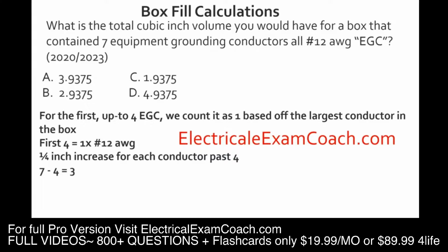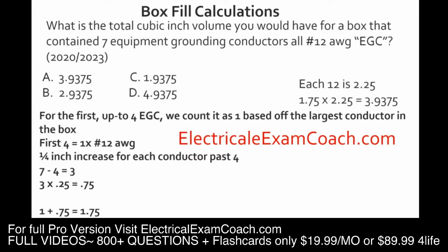We have 7 total, and we're going to minus 4 because those first 4 we counted as 1. So we have 3 left over, and we're going to take those 3 and multiply it by a 1/4, and that gives us 0.75. So we have a total of 1.75 conductors based off whatever the largest conductor is in the box. In this case, there's only number 12s. So we would take that 1.75, multiply it by the cubic inch volume for a number 12 conductor, and we end up with 3.9375 cubic inches for our equipment grounds.